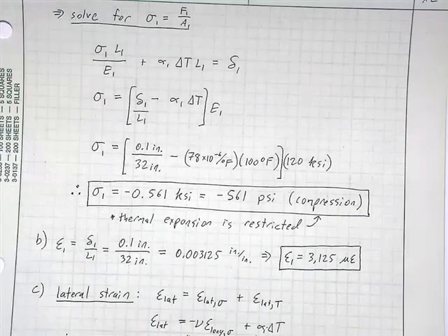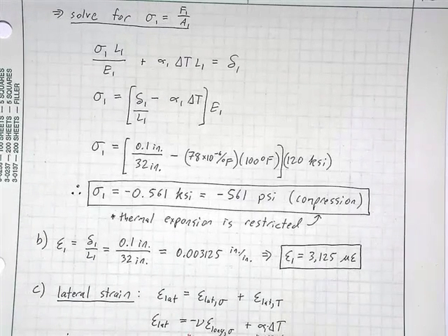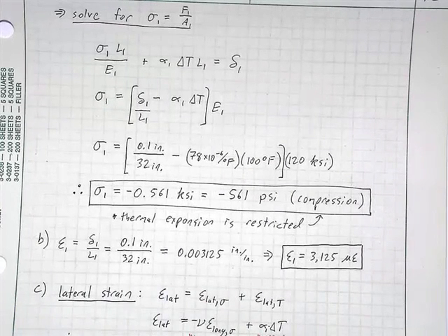And this is actually a result of, well, we have a really low stress, but a pretty high strain, and that's what I was saying with the polyethylene having a very low elastic modulus compared to steel, which is about 1,000 times bigger of an elastic modulus. So this is not very stiff. So even for a low stress, it has a really high strain.